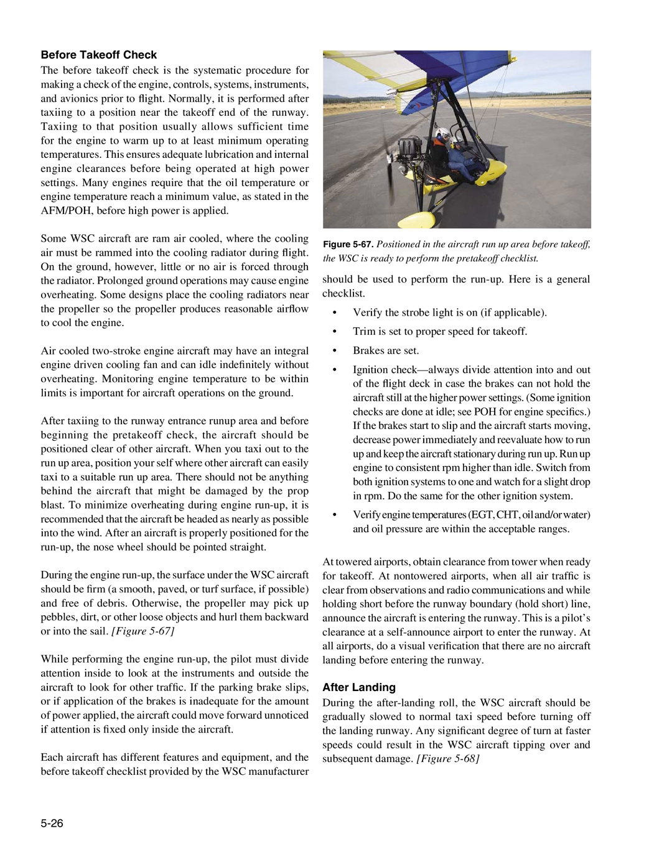After taxiing to the runway entrance run-up area and before beginning the pre-takeoff check, the aircraft should be positioned clear of other aircraft. When you taxi out to the run-up area, position yourself where other aircraft can easily taxi to a suitable run-up area. There should not be anything behind the aircraft that might be damaged by the prop blast. To minimize overheating during engine run-up, it is recommended that the aircraft be headed as nearly as possible into the wind.